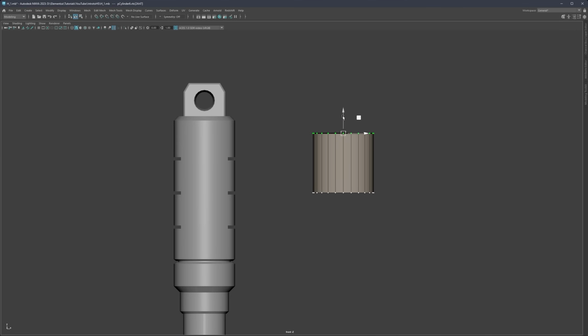So now when you're in move mode and you hold V, you can click on various points where you would like the move height to stop. If I just hover on this point right here, it's going to stop there and align perfectly, or go up or go here. It really doesn't matter. And the same thing down.